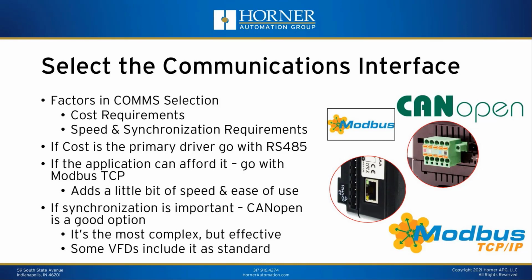It's there. You might as well use it. So which network are you going to choose is the big question, right? Because you could choose RS-485 Modbus, which is built in to most drives. You could choose an Ethernet-based connection like Modbus TCP, for instance. You could use a field bus type option like CANopen or EtherCAT or something of that nature.